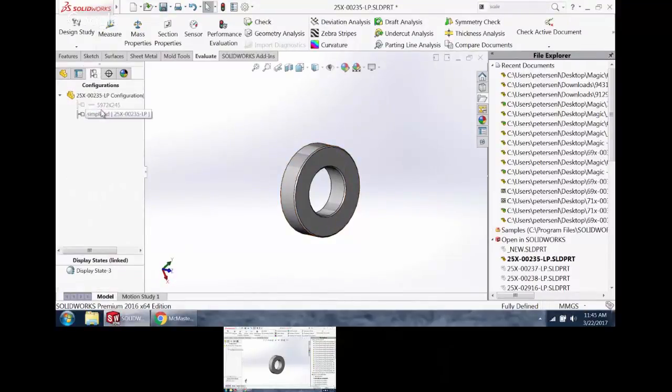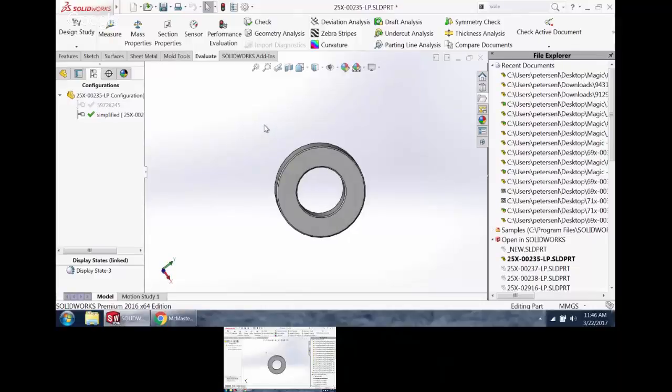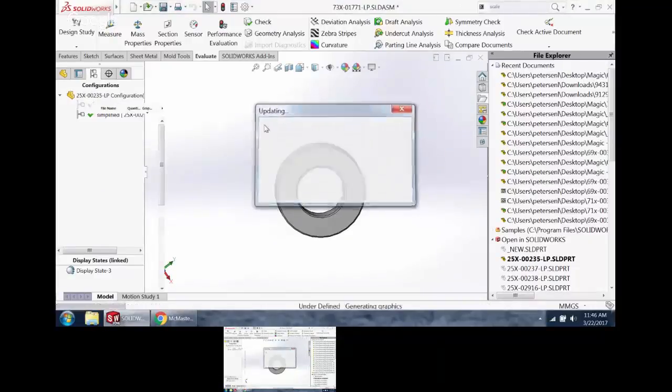Or I can still have the full version if I need to do it for renderings or whatever reason I want to see the balls inside the ball bearings. I could still have it there and then just use the configuration at the assembly level to make it run faster.